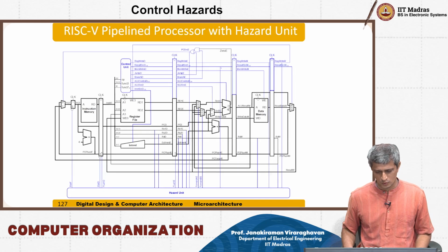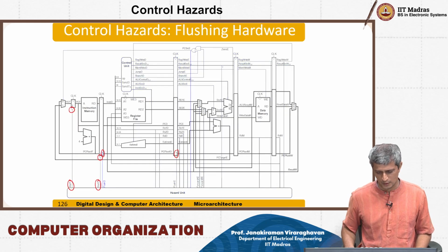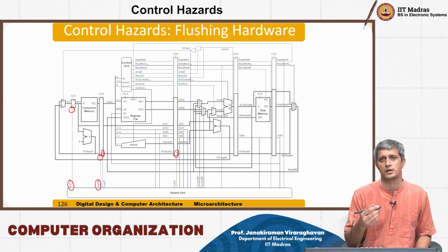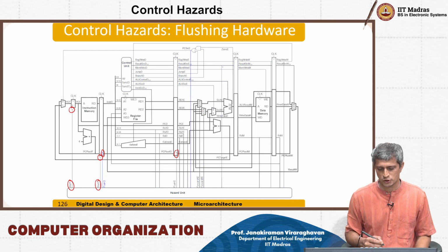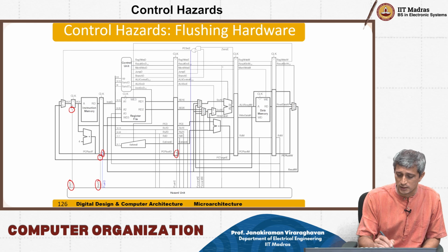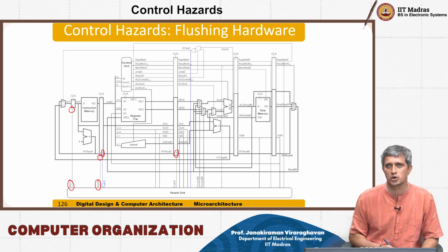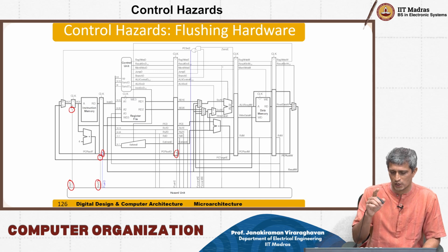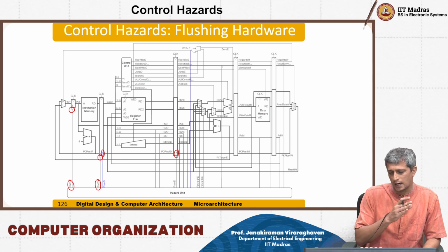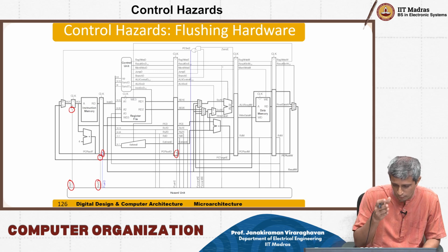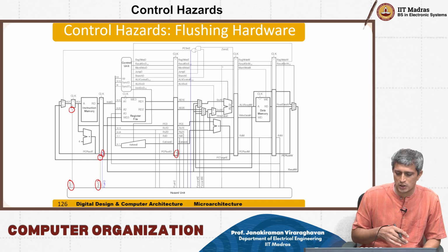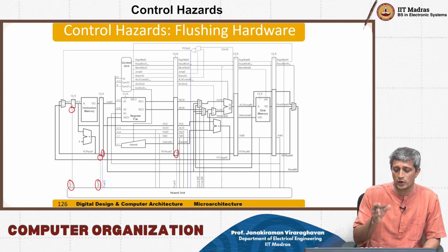And therefore this is a very valid implementation of a flip-flop with a clear signal. So now let's get back to this unit, the flush and stall unit. The flush signal is controlling the clear. You want to clear when flush goes high, and therefore make the output of that flip-flop go to 0. On the other hand, the stall is controlling the enable.